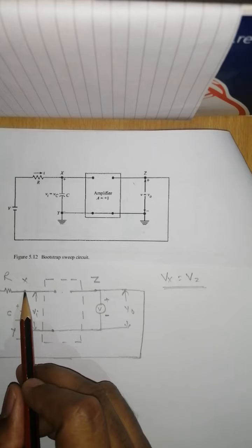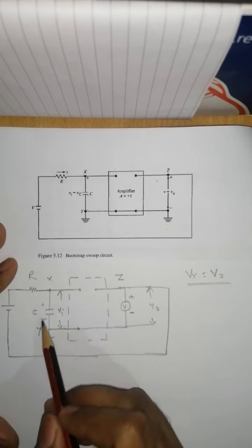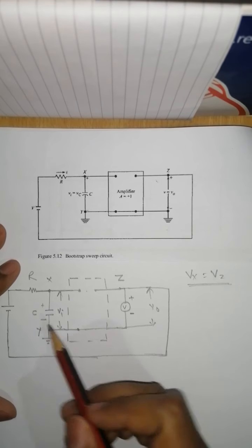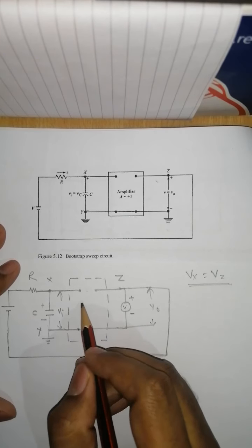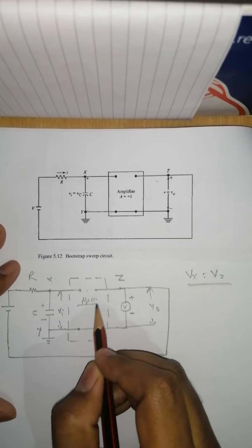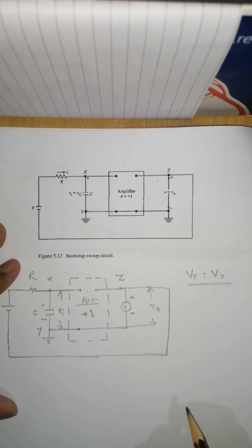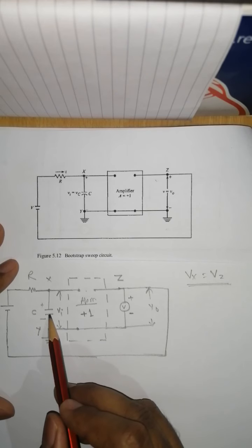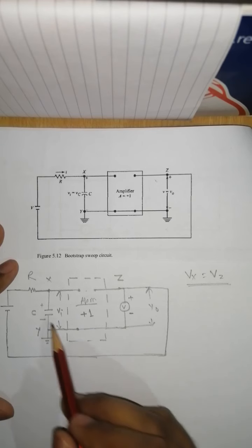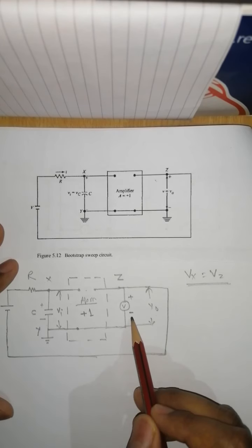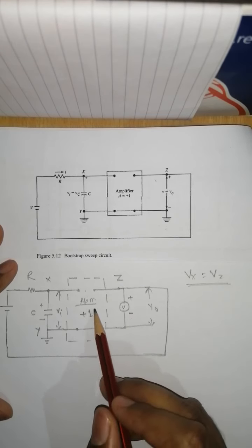Here the input is available at the X terminal and the output is available at the Z terminal. It means that whatever input you apply here, the same output will come across this output terminal. So this is like an amplifier, but the gain of this circuit will be +1 only. Then only this input will appear at the output section. The input multiplied by this gain turns into the output voltage. So this circuitry is an amplifier with a positive gain.